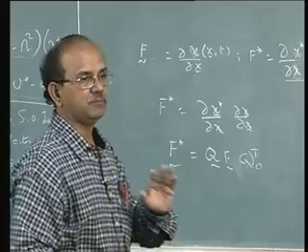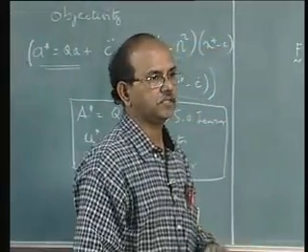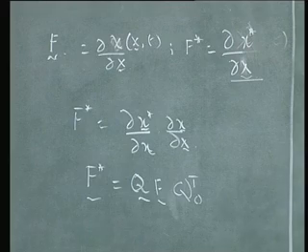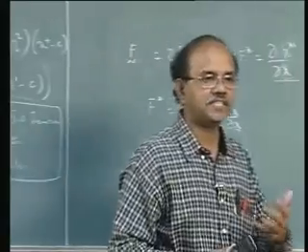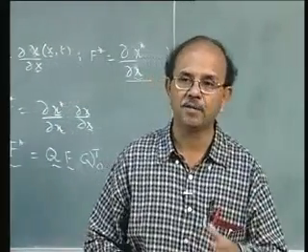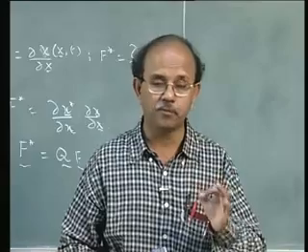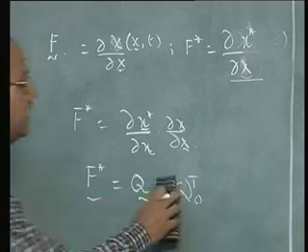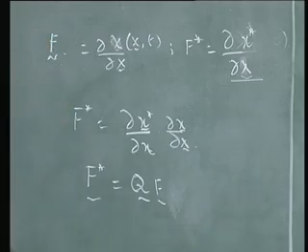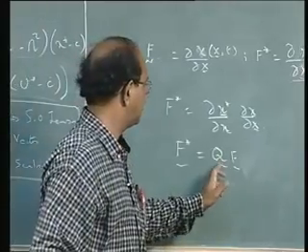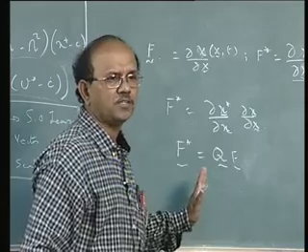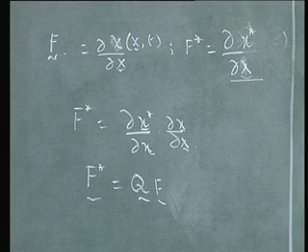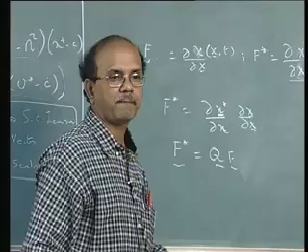But in most continuum mechanics literature, you will find that the two observers have the same X or same reference configuration. Very important to understand that, and hence F star is equal to QF, or Q is the only thing responsible for variation of F. So this is also called a two-point tensor, if you remember, and two-point tensors transform in this fashion.